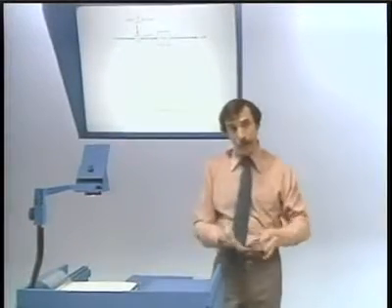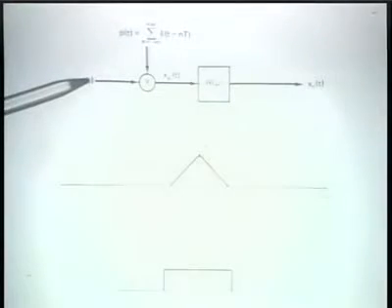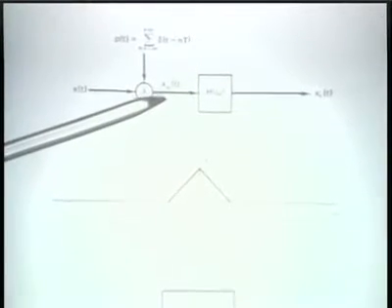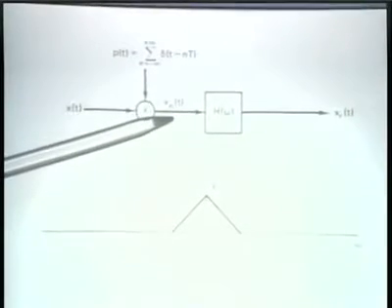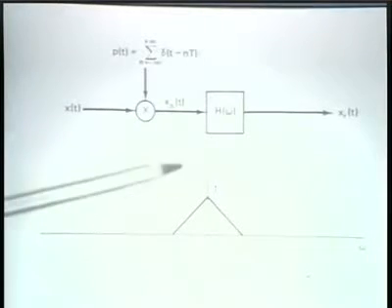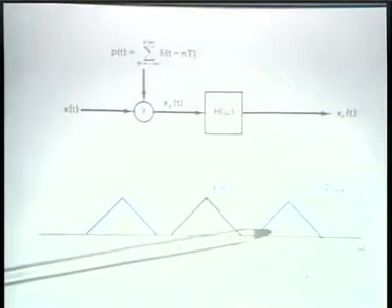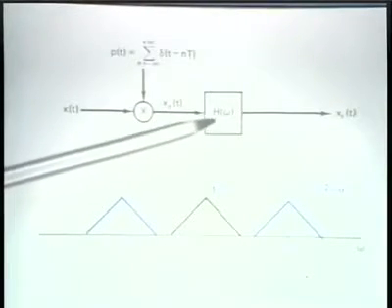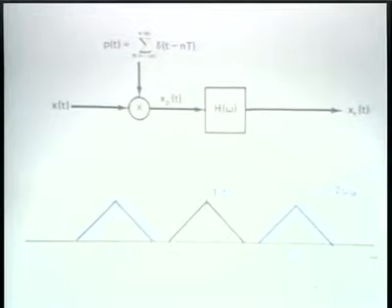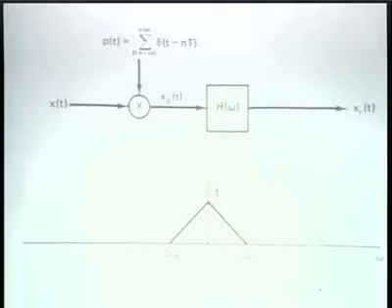And finally, to remind you of the argument once more, if we have an original signal and its spectrum, when we've sampled it, this is now the sampled signal, an impulse train whose instantaneous values are samples of the original waveform. The spectrum of that is the original one replicated, and when that is processed through a low-pass filter to extract this part of the spectrum, then after the low-pass filter, we can recover the original signal back again.